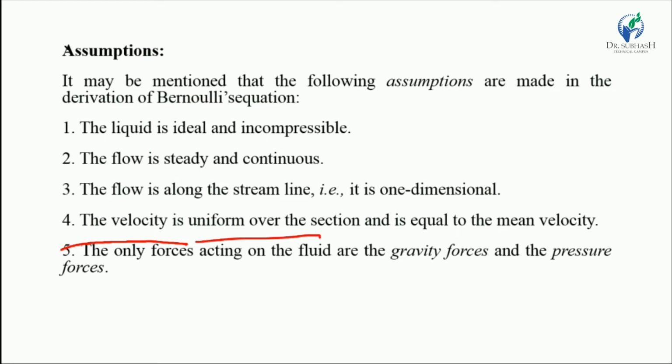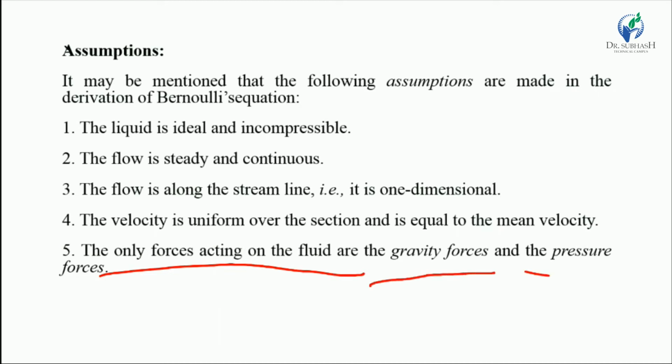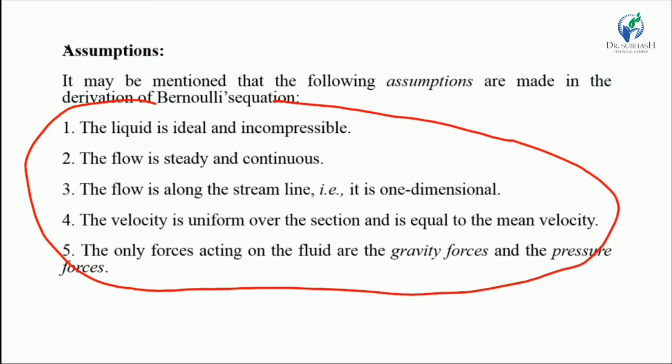Velocity is uniform over the section and equal to the mean velocity. The only forces acting on the fluid are the gravity force and pressure force. Only two forces are considered, losses are not considered. Okay, these are the assumptions considered in Bernoulli's principle.